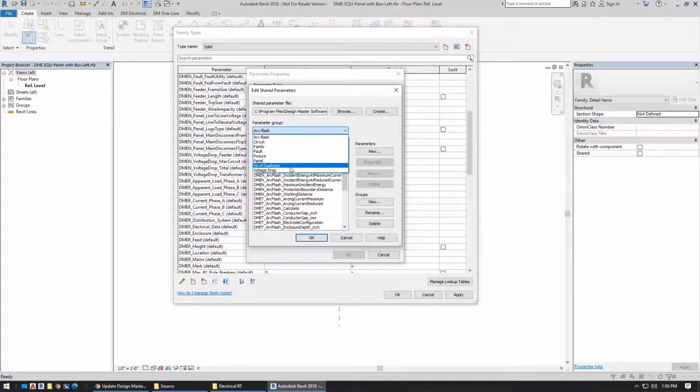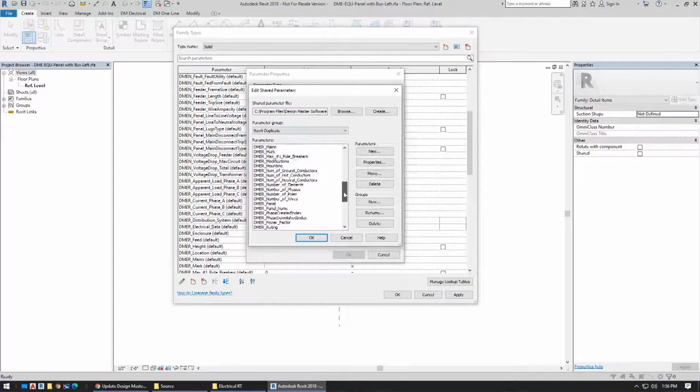The Revit duplicate, these are all the Revit properties on electrical equipment and electrical fixtures that we have duplicate shared parameters that you can use. So basically this would be the apparent current property from Revit, the circuit number property from Revit. So we just pull in the things that they have defined, and we are able to display it then on your one-line diagram.